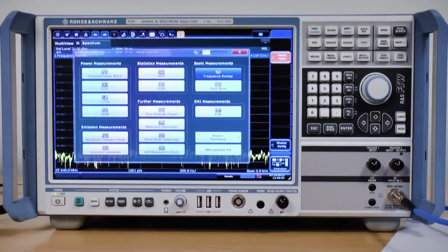With spectrum analyzers relying heavily these days on processing technology, they often contain many inbuilt routines. These cover many functions, everything from channel power to harmonic distortion, and third-order intercept to AM modulation measurements. Two routines that deserve special mention are phase noise and spectral emission masks.